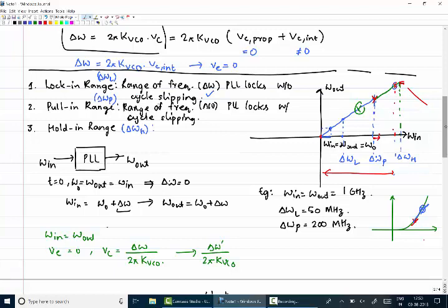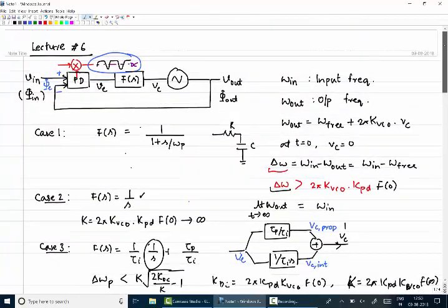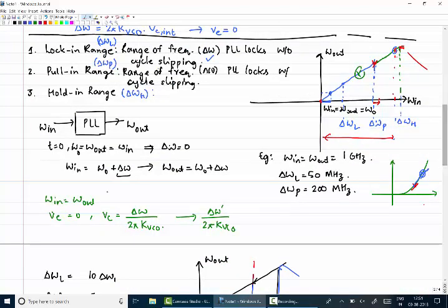Okay. So coming back to this PLL block diagram, I said that after omega pull-in, if the frequency step is larger than omega pull-in, it is not able to acquire the required control voltage, error voltage, or the phase error. But at the verge of the omega pull-in, if you give a small step, it is able to acquire slowly. You need to give time to it, right? So now the question, see, one way to simulate for the hold-in range is the way I have told you.